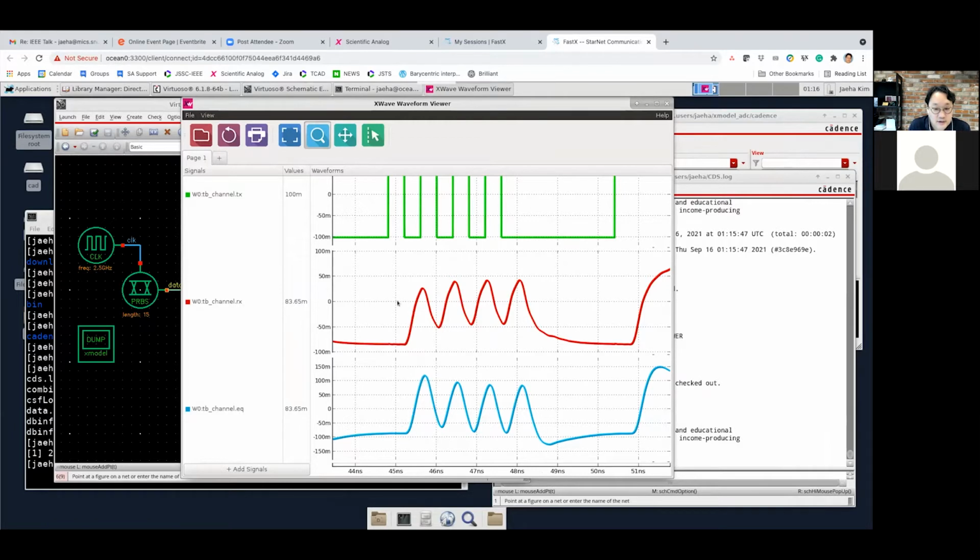So as you expected, you see these very smoothly varying continuous time waveforms because of the continuous time filter behavior. And what's notable here is that these markers indicate where the events have been triggered during the SystemVerilog simulation, which is actually very sparsely distributed.